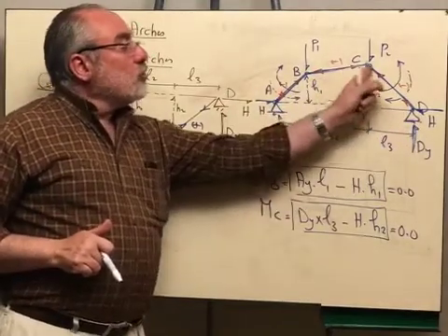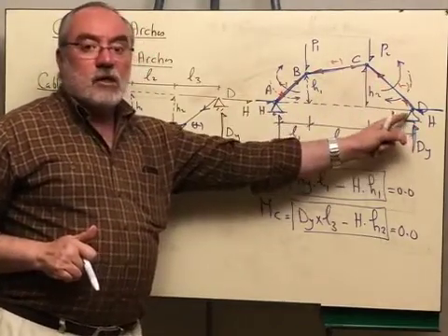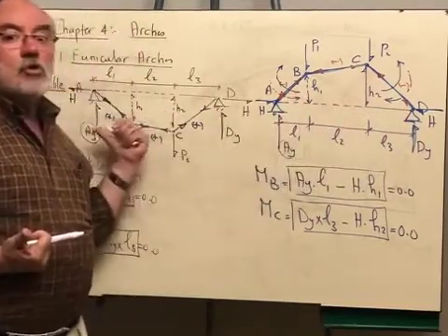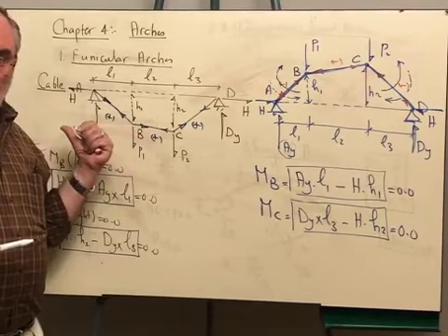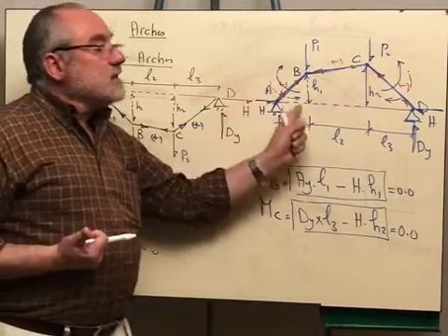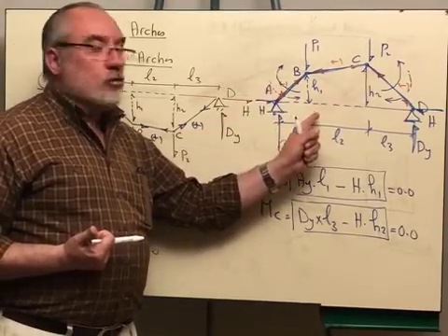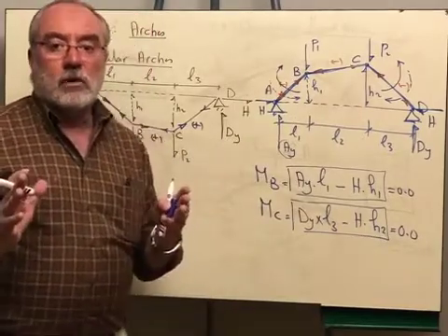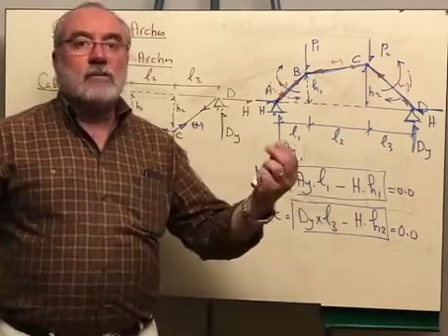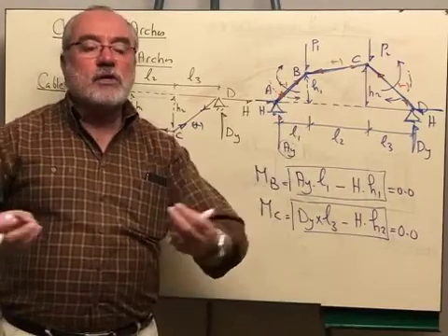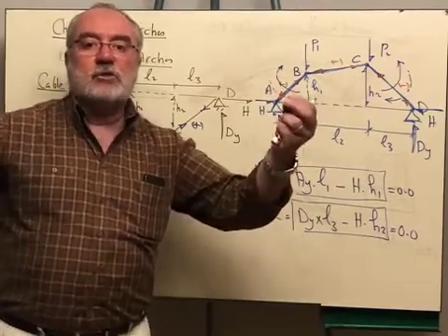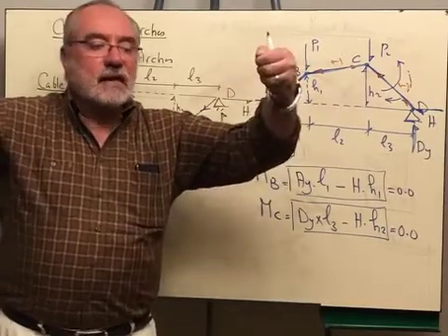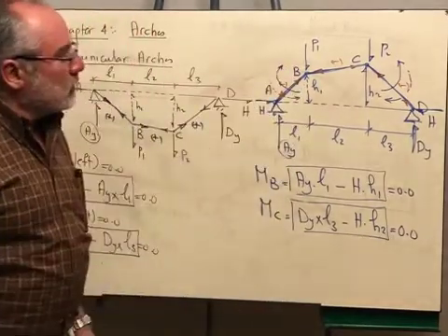The internal forces that will be developed will be compression instead of tension, with the same magnitude as the tension. And we have 0 shear force and 0 bending moment. So if I want to form a funicular arch, I would imagine what the shape of the cable would be when it is subjected to this kind of gravity load, and I will reverse this exactly in order to get a funicular arch.